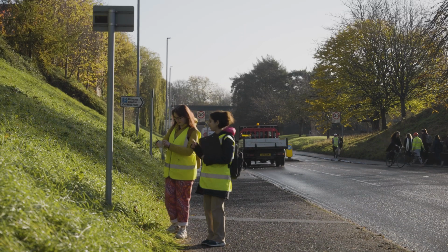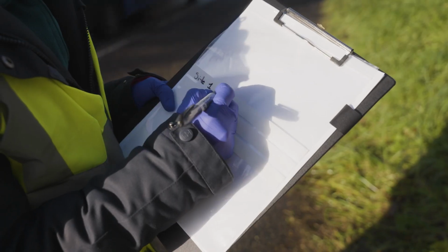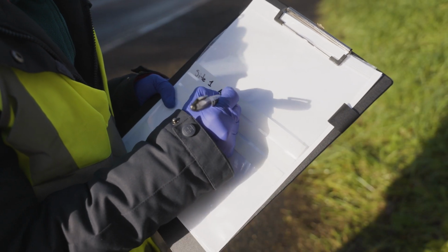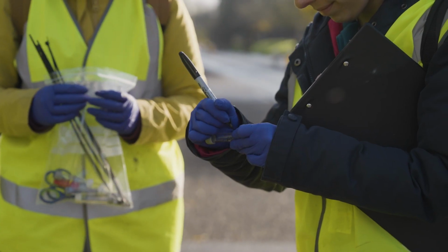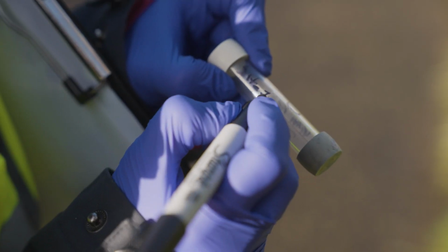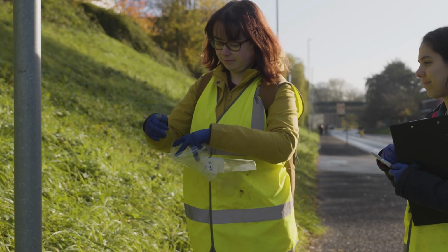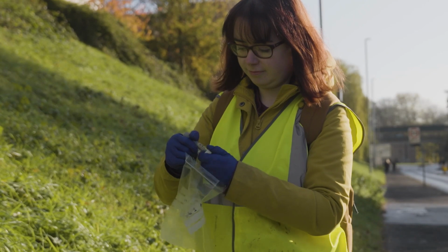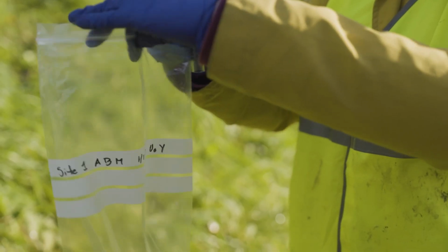With passive sampling, you should choose a suitable place to leave the sampler to prevent theft and disturbance. Carefully consider the location and placement of equipment in terms of pollutant sources. You could also place multiple samplers at the same site to improve accuracy of results.